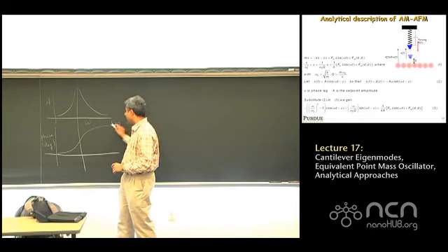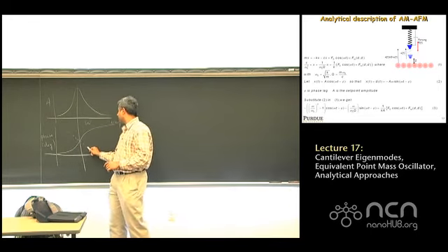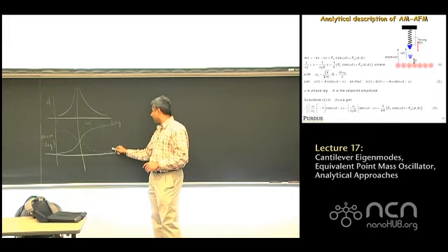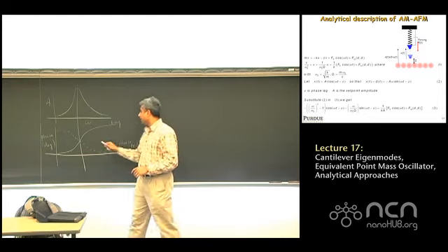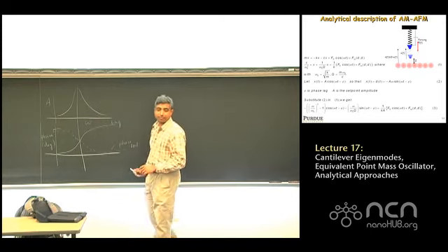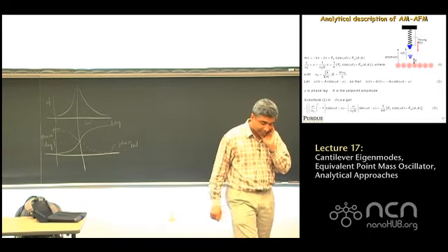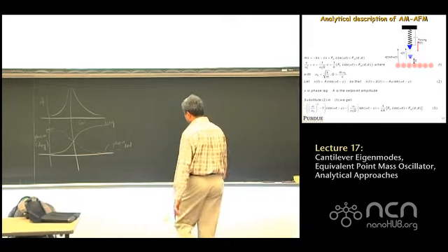On the other hand, if the tuning curve does this, something like this, right? Then it'll be phase lead. Right? And it'll be typically a negative value. And it'll get more and more negative. So just by looking at the shape, you can tell if it's plotting phase lead or phase lag. That's the easiest way I would suggest to check.